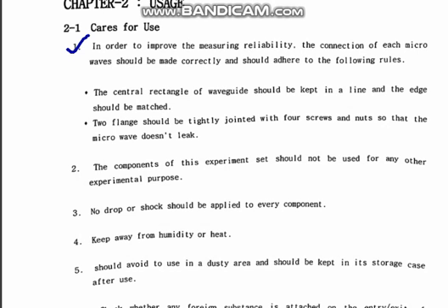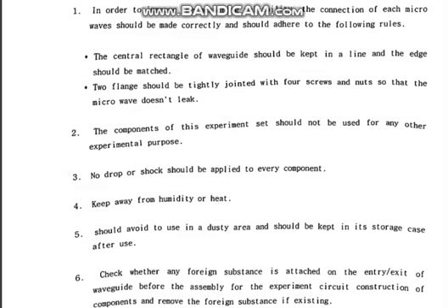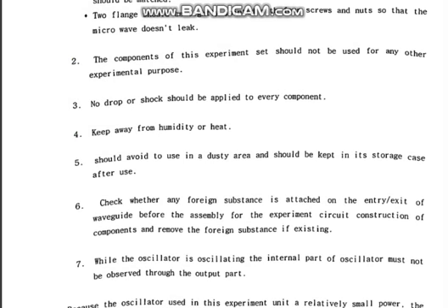The second one is that the components of this experiment set should not be used for any other experimental purpose. No drop or shock should be applied to any component. Keep away from humidity or heat. Avoid using in a dusty area, and components should be kept in their storage case after use. And check whether any foreign substances are attached on the entry and exit of the waveguide before the assembly of the experiment circuit, and remove the foreign substance if existing.